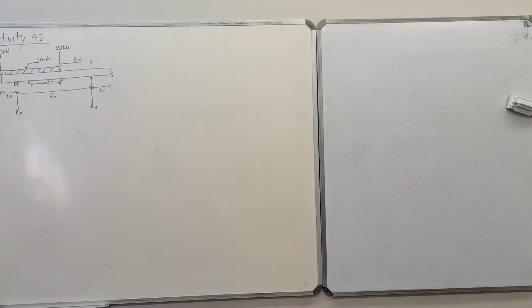That's its magnitude. Normally we multiply it by its distance to give us a concentrated load. They don't give you a weight or gravity, so you can disregard that. You have two supports, one 1 meter from the left, the other 1 meter from the right. Full length of this beam is 8 meters. Everybody's okay with that?